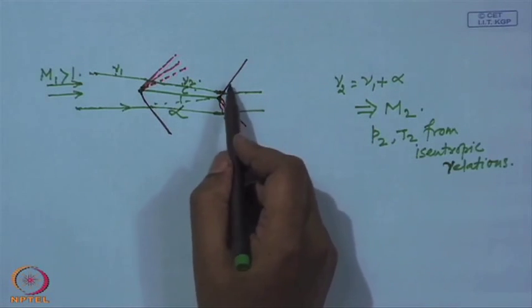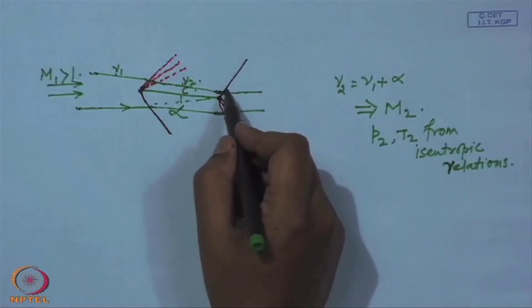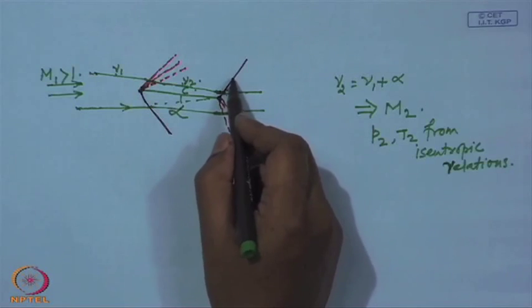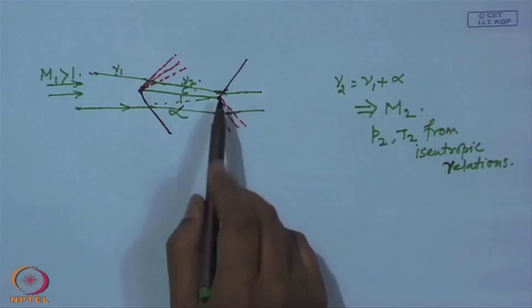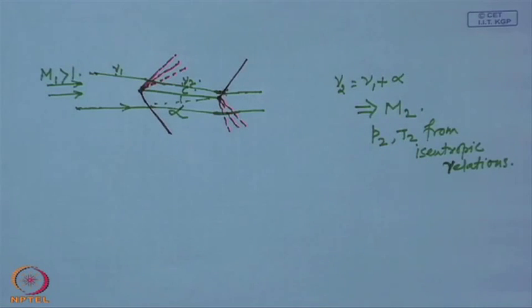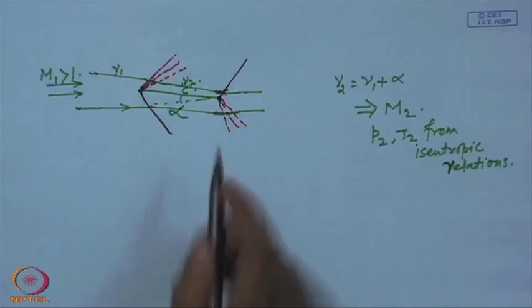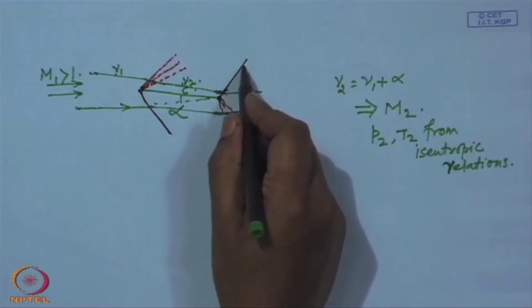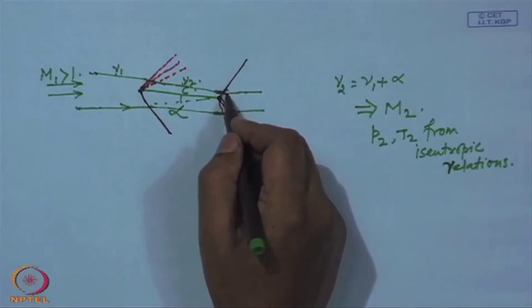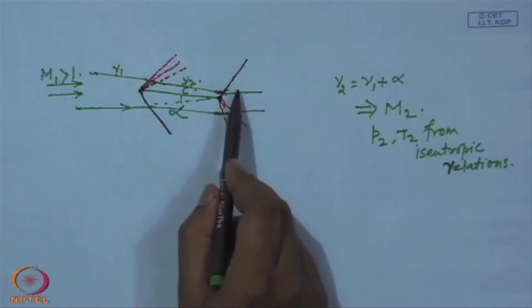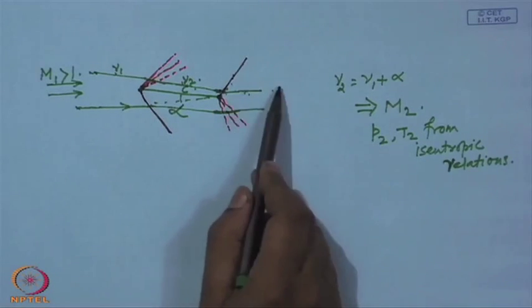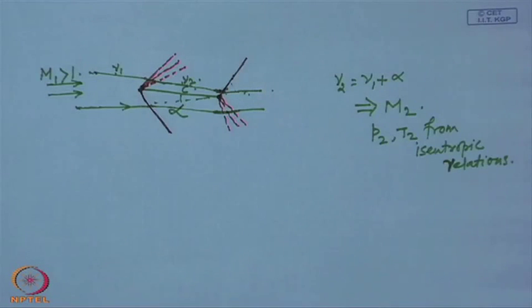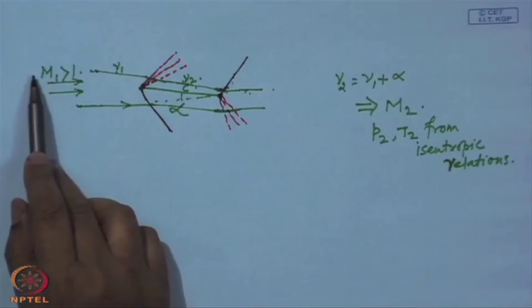And again knowing the flow turning angle alpha here and the Mach number ahead of this shock M2, using the M-theta-beta relation or the M-theta-beta chart, we can find the wave angle corresponding to this shock, and once that beta for this shock is known, we can calculate the pressure, temperature, density, all other properties downstream. The pressure of course should be the upstream pressure.